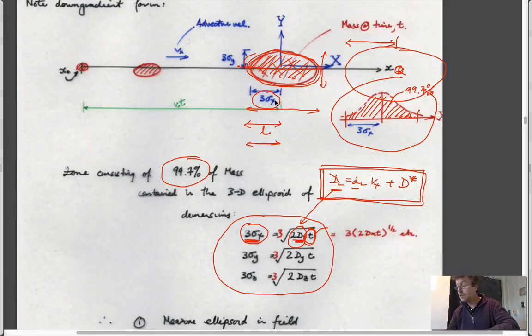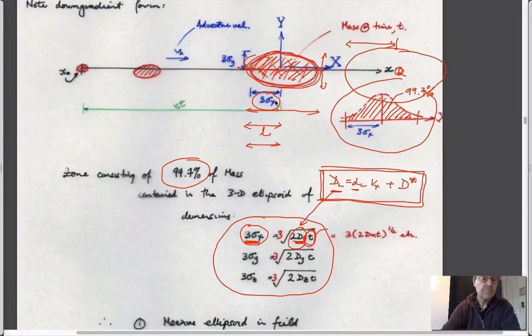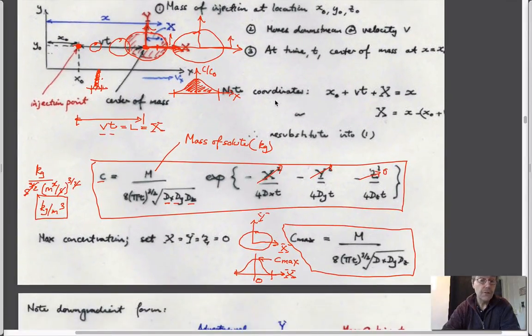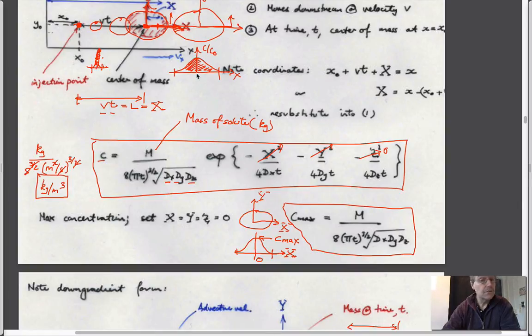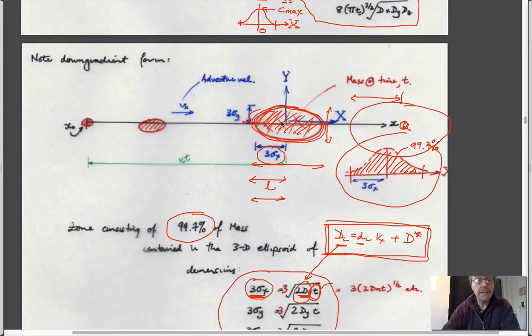So we have an advection dispersion equation. We know that accumulation is equal to a mixing part and an advection part. We know kind of what each of those components are. We can break it up into two important physical properties: Peclet number, which relates the advective flux to the dispersive flux, and pore volumes when looking at the one-dimensional flows, and those make some sense, hopefully. And when we look at three-dimensional flows in an aquifer, we can look at it through, again, the similar concepts, where you look at just spreading around a center of mass as it goes downstream, and we can calculate some features of that in terms of the length of the cloud and the width of the cloud after some particular length of time that's been traveling. And if we know what those lengths are, we can use it to back calculate what the properties are.